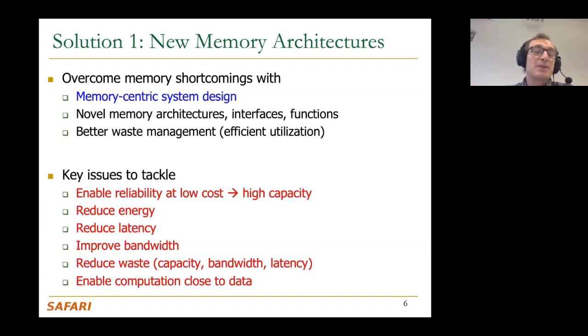Energy is also less of a problem because, again, you're not exercising these huge interconnects that exist between the processor chip and the memory chip. But trade-offs still exist at the same level. You still want to improve these things, but the benefit you get from improving those things on chip is much less today, because fundamentally it's on chip and everything is smaller, let's say, to deal with.